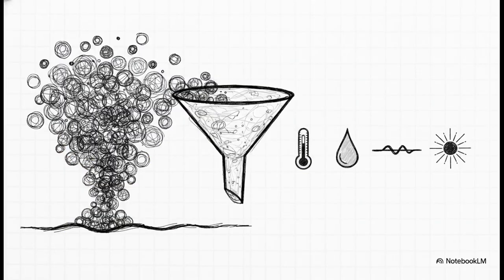To mathematically tame all this intense chaos, specifically aiming for that preferred nucleate boiling phase, engineers rely on the famous Rohsenow equation. They carefully plug in precise variables like liquid viscosity, temperature excess, and surface tension to prove that even in the middle of thermal chaos, everything still obeys these strict laws of physics.